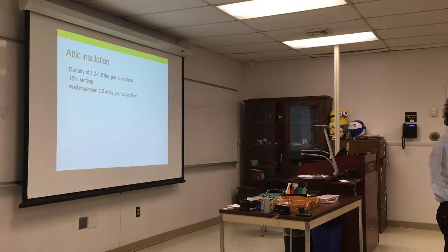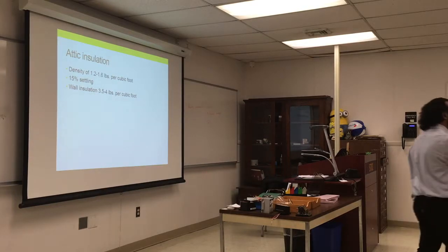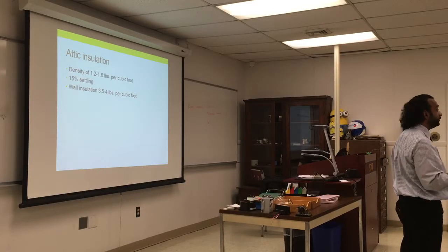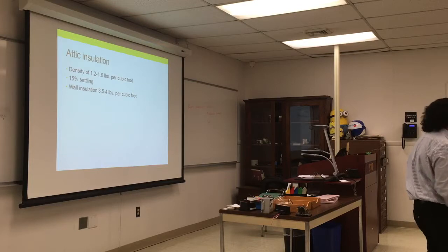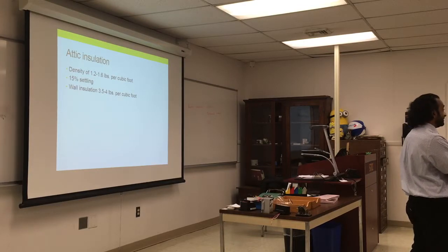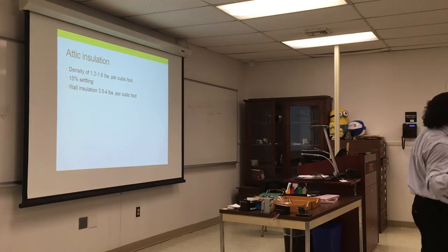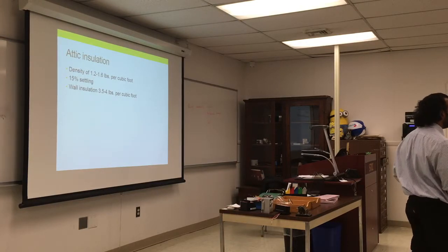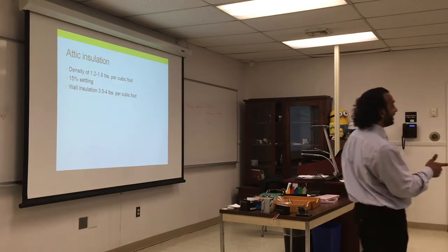Why do you have the gable vents? The gable vents help with ventilation in the attic. That's a different thing. That's for cooling, in the summer. You vent from the attic outside, and the air from the house comes out. That's completely acceptable for cooling. But venting exhaust from the house, from the dryer or the oven, into the attic is not a good idea. But I get what you're saying.